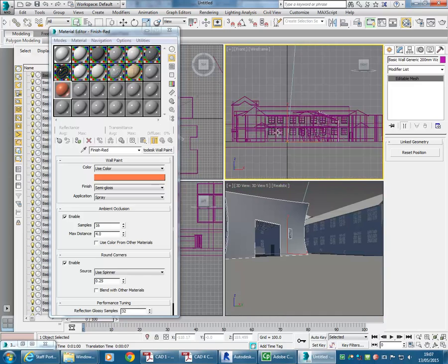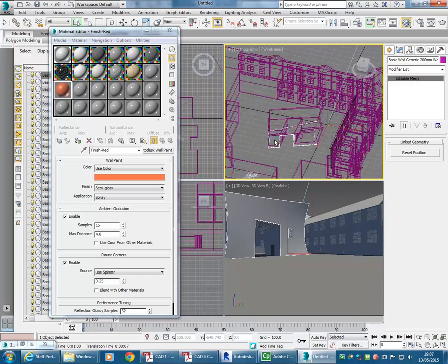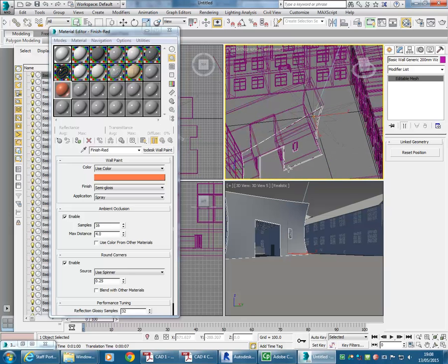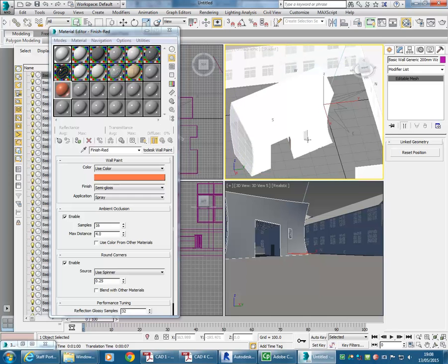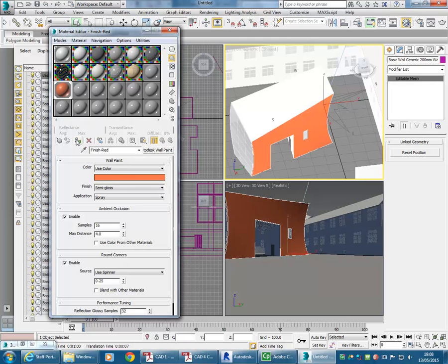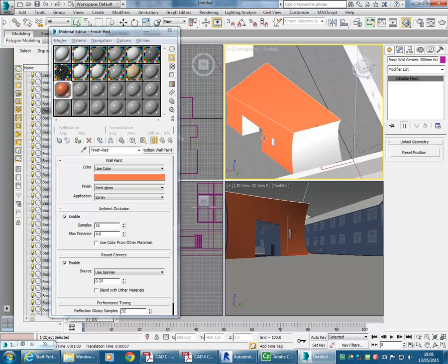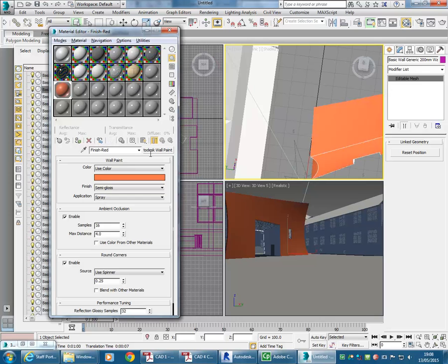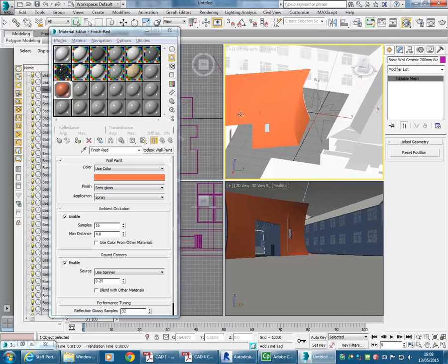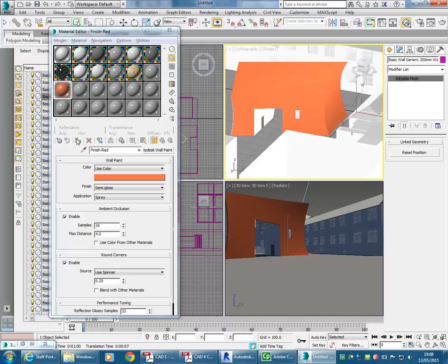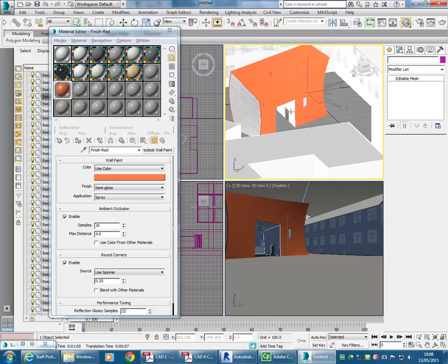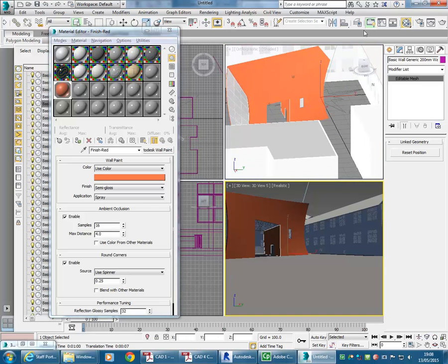So I'll just go to another view actually to get those, and make that one shaded as well. So just with that wall selected now, I can use this button here to assign a new material. I can select each of those surfaces and just manually assign that material. So that's like your paint tool in Revit. There we go.